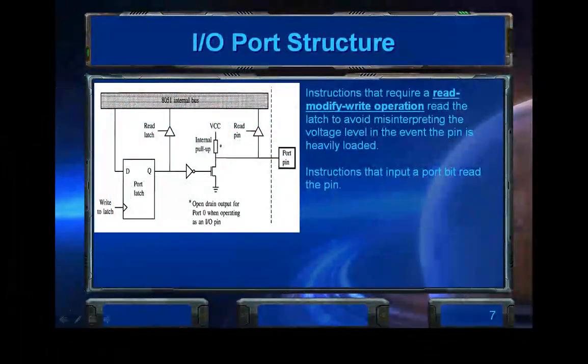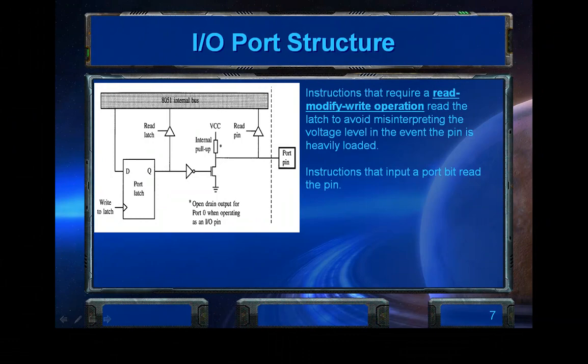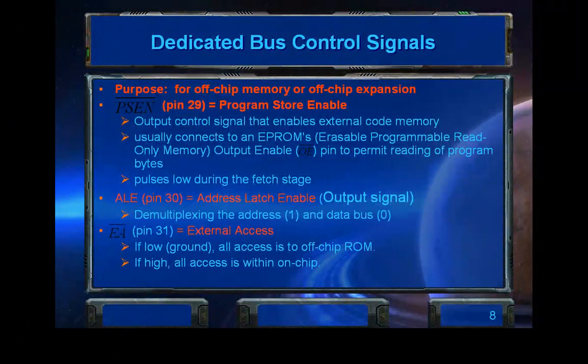The structure of the I/O ports are as shown in the diagram. Instructions that require a read, modify, or write operation read the latch to avoid misinterpreting the voltage level, in the event the pin is heavily loaded. Instructions that input to a port bit read the pin.